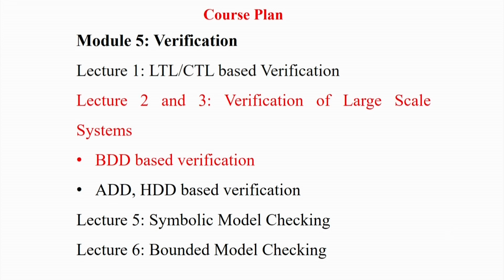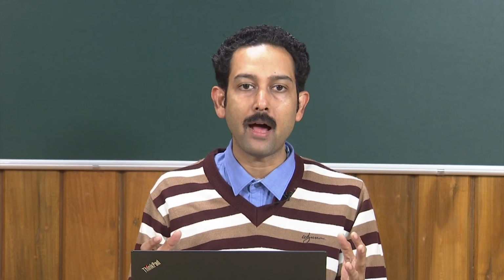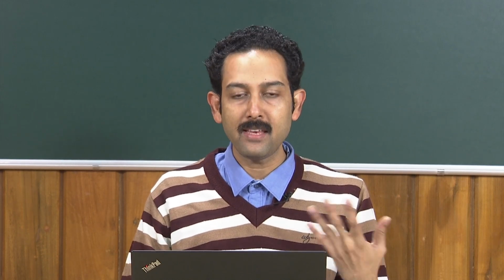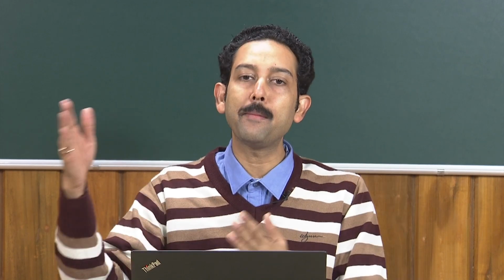that is to understand basic model checking before we can go to optimization techniques for verification. So, what we had seen in that lecture is that we have to have a formal model, that is a state based model for the system you want to verify, and then there will be some LTL or CTL formulas which will be your design intent. That means, for example, if you switch on the heater or the microwave, after some time it should start heating.